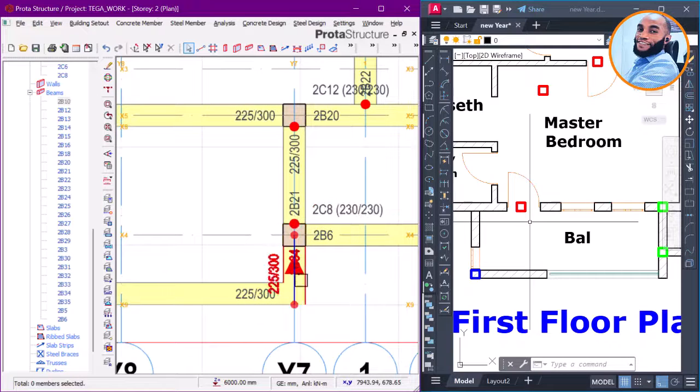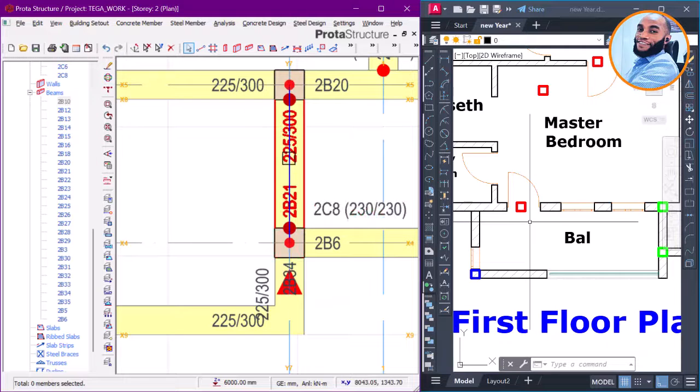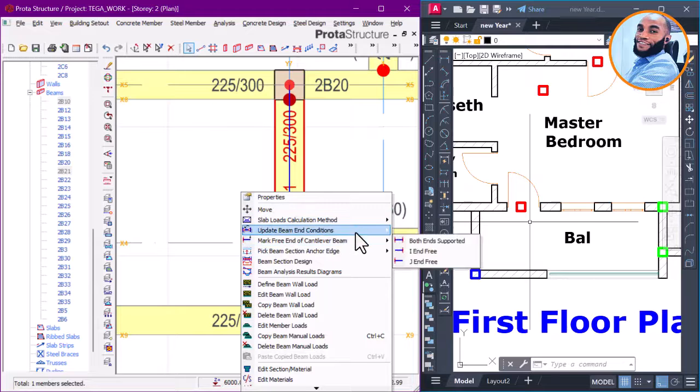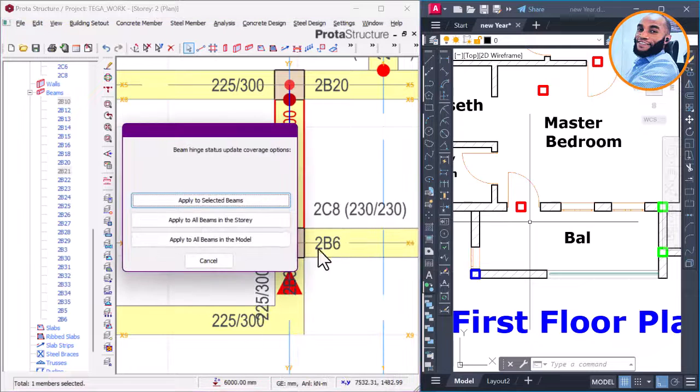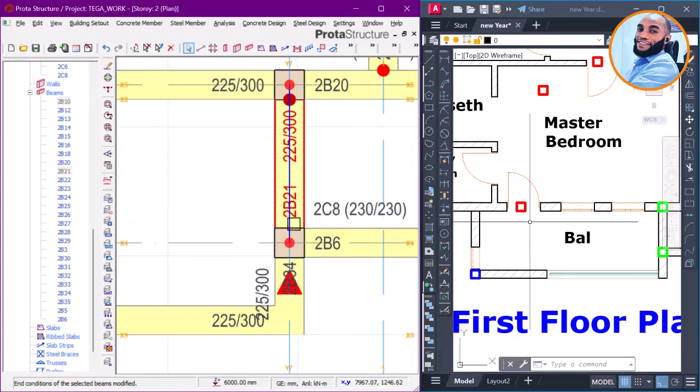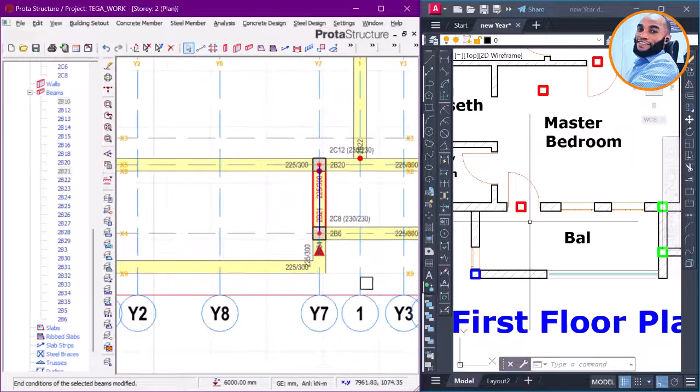Whenever you have a cantilever beam at the front, don't always hinge the next beam coming at that point. So I'll have to remove the beam hinge here on the I side, and hinge only on the J side, which is up here, and don't hinge here because the cantilever beam is here. Okay, that's fine. There are principles on this. Okay, so right now, I'll go again.